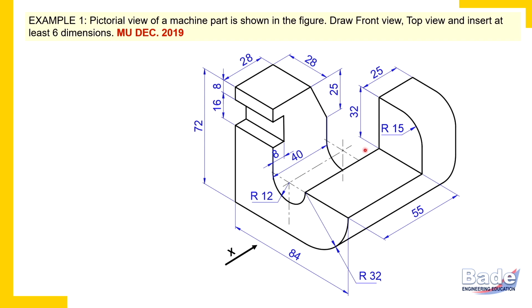Okay, watch the diagram. It is not a symmetrical object. Also, it's not an object in which we can identify parts which are assembled or connected together. It's one single block bounded by different surfaces. The first approach we studied in the second video on orthographic projections, that is, we'll check the principal surfaces and principal edges first to continue with front view, top view and side view.